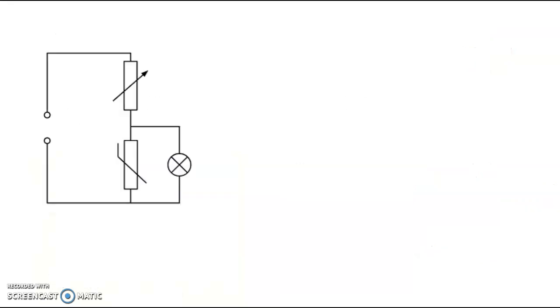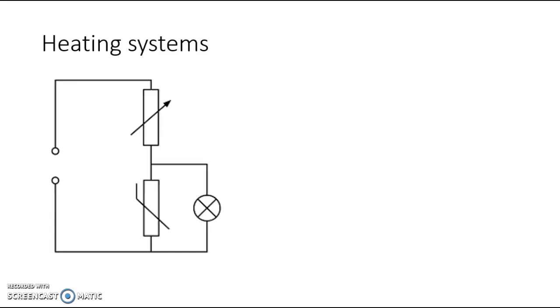So it's quite important to understand that key fact, that as you increase the temperature, resistance decreases, therefore the current flow increases. So let's take a look at one of the applications where you've got a circuit like this. This is an interesting circuit that's usually found in heating systems. If I've got a cell here, the cell will have a particular voltage, so let's call it V total. You would recognize this symbol. This is for the thermistor. The thermistor is attached to, we could call this a bulb. You could have a heater here. It's important to note that these two are in parallel.